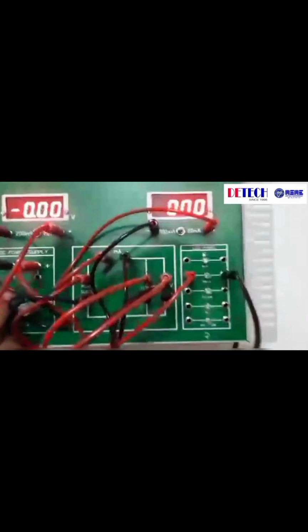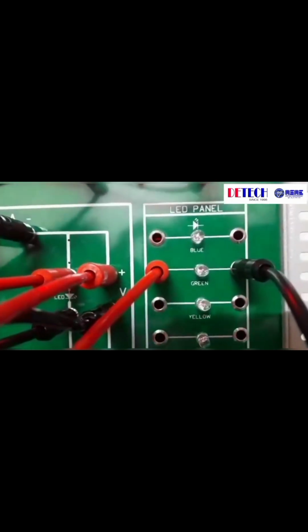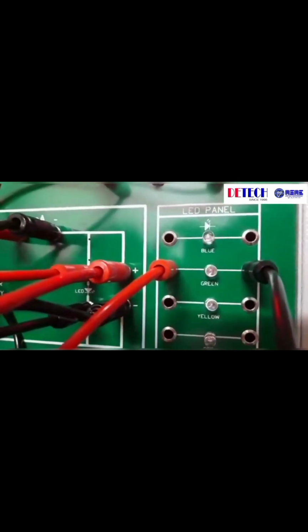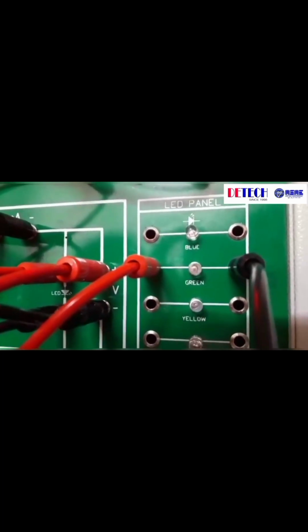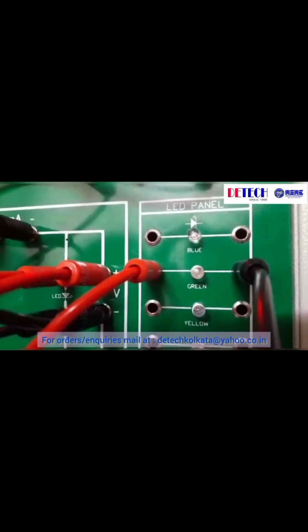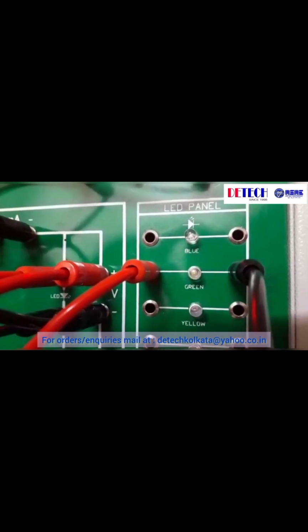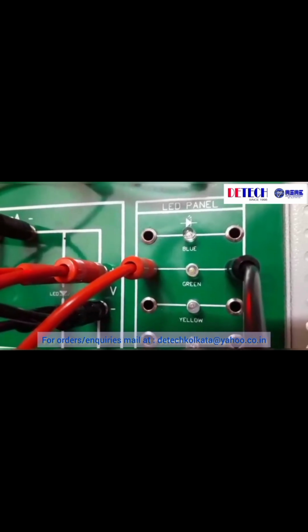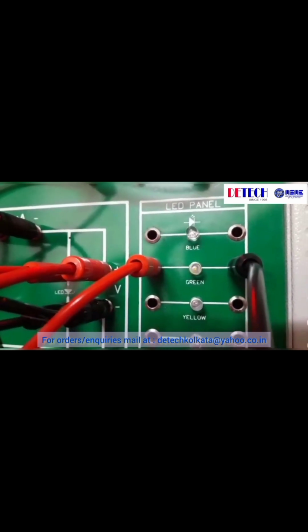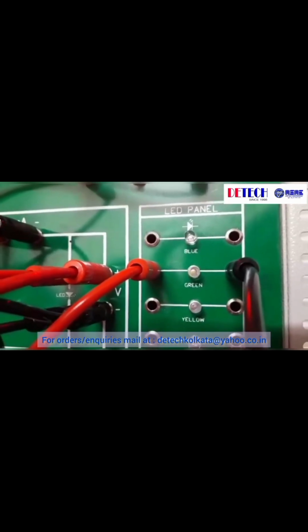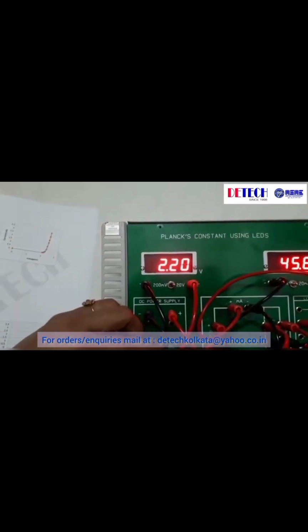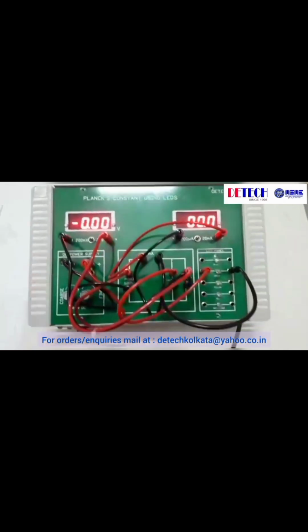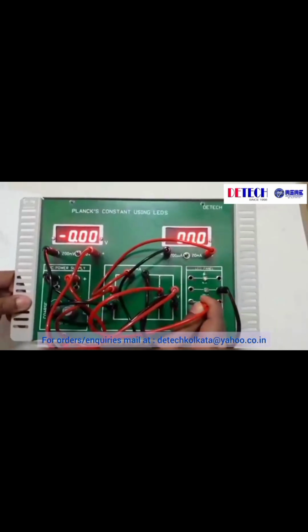Again zoom into the green one and we will see what is the voltage when the LED just starts to glow. It has just started to glow. So the current, yeah, it's glowing, right? Yeah. So the voltage is around 2.20 volt. Current is 45 microampere. And for the yellow LED,